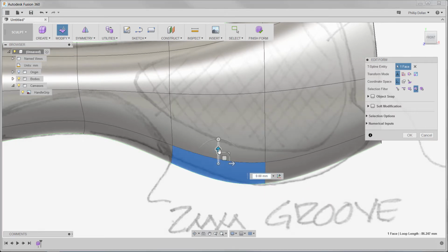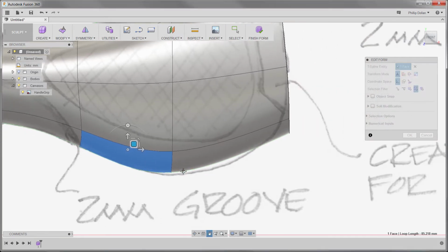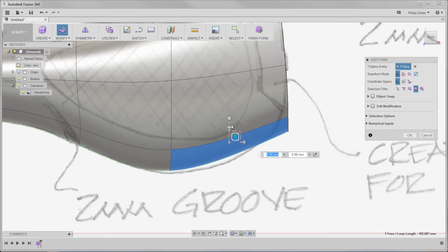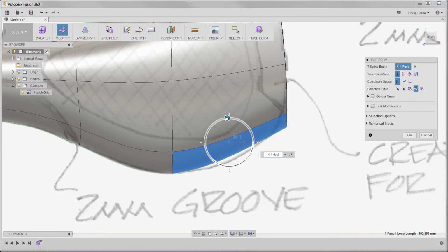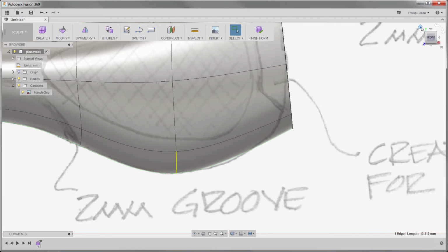A little bit too far, so drag that back up and rotate somewhat. Select that last face, rotate it around until it matches, and drag it into position. So you can spend a fair amount of time on this, but keep in mind that sketch in the background is an approximate sketch.